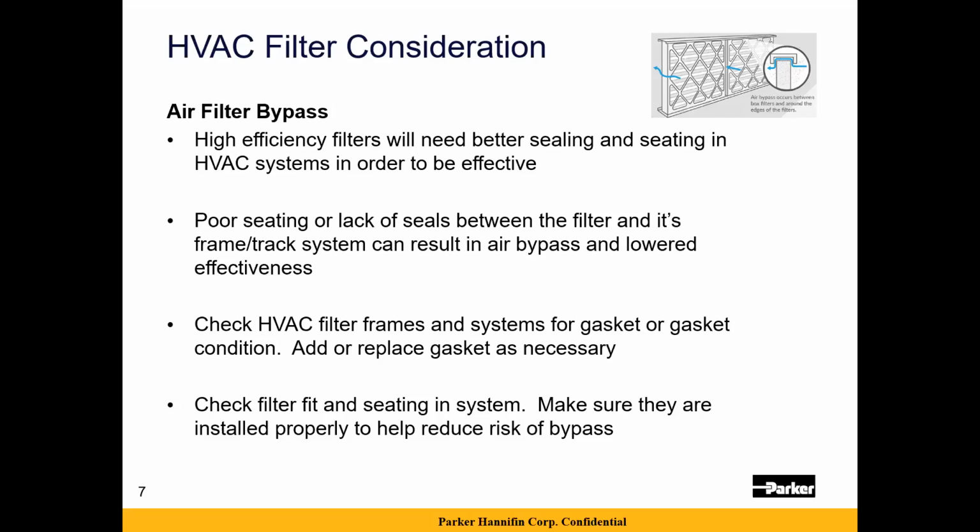So when looking at improving efficiency, you might want to also check the filter frames to see if they're in good condition and to see if gasket might need to be added as an aftermarket step. Gaskets are readily available in a lot of hardware stores. Some of your sites may have gasket available or weather stripping, and those kinds of materials can be used to help gasket tracks and get a better fit and seal for the filter.